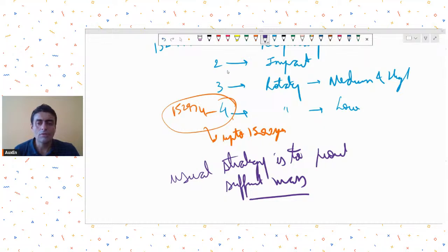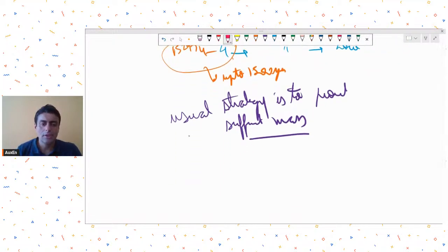But over here, in case of buildings, if you try and go for three times, four times mass, your building or your slab may become so heavy that your beam column sizes, everything will increase. So in such cases, I think it will be best to install some dampers. Rubber dampers or viscoelastic dampers or whatever, or bearing pads which will dampen the vibrations.